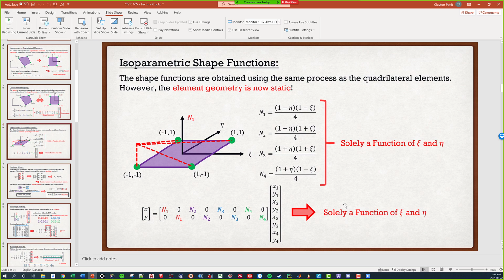We define two things. One is I create basically a giant vector or giant matrix containing my node number and then the coordinates of each node. For example, node 1 has coordinates, let's say, 3, -2. So my entry would be 1, 3, -2. And I go on to node 2 and do the exact same thing, and in the end I create a giant matrix of all my nodes, their number, and their location.